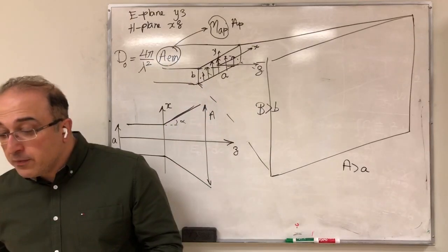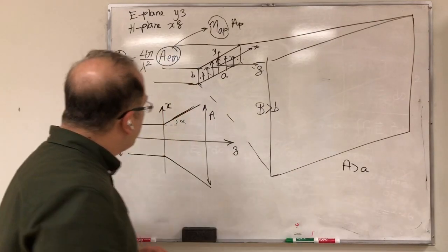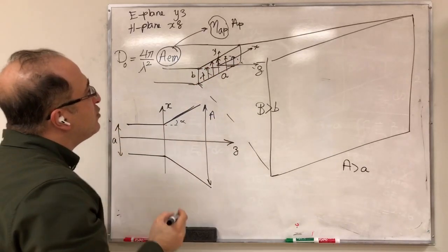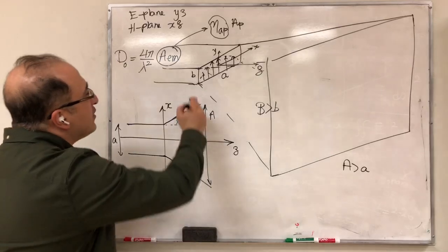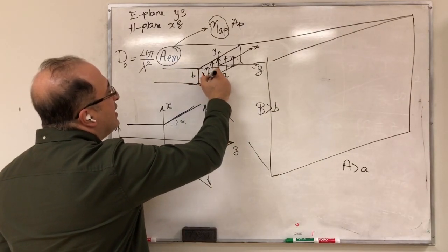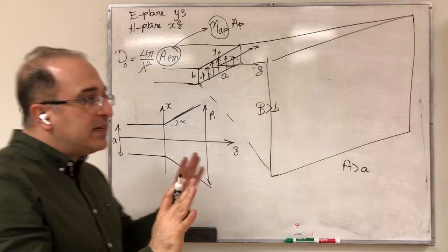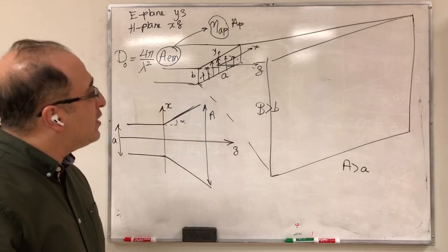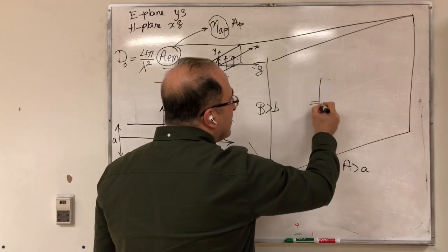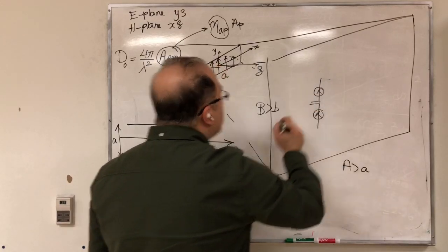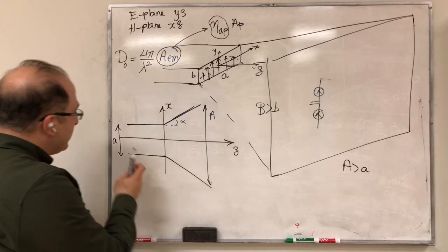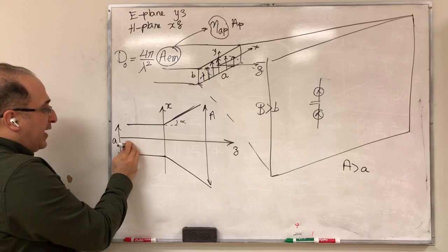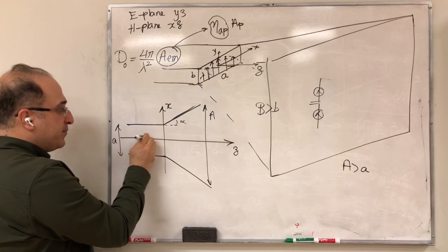So this is what we want to address here before getting to the design of the horn antenna. If you look at this open-ended waveguide, or waveguide distribution in its fundamental mode, these electric fields in the waveguide are in phase with each other. When they are in phase with each other, it helps you get very good radiation perpendicular to the antenna. This is also very similar to a dipole antenna, where you have these two in-phase currents. Now you have a set of in-phase electric fields. These are the electric fields, so they're essentially out of the whiteboard, and they are traveling together like this.